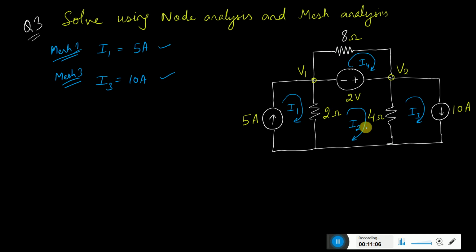Again, I just need to find the mesh current over here. So let us write the equation for mesh 2. Because I am moving in this direction, all my sign convention will be like this. Here there is no sign required, here only minus, and here plus and minus. And this is a voltage source. If I move from here, I see the plus first, so 2. The current here is a subtraction, because I2 is there and I1 is subtracting, so I can write I2 minus I1.